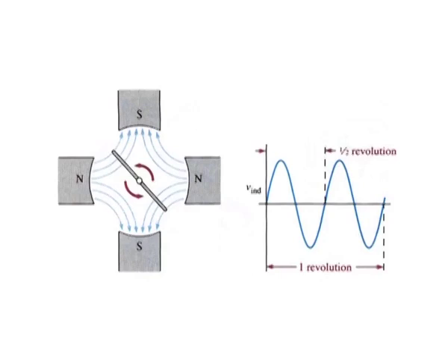The voltage induced in a conductor depends on the number of turns and the rate of change with respect to the magnetic field. Therefore, when the speed of rotation of the conductor is increased, not only does the frequency of the induced voltage increase, so also does the amplitude, which is its maximum value. Since the frequency value normally is fixed, the most practical method of increasing the amount of induced voltage is to increase the number of wire loops.